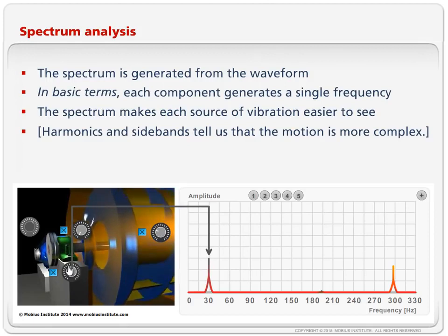But anyway, if I take one measurement and then I come back later and I see 30 days later it's like this, 60 days later it's like this, I can say, okay, the unbalance is growing. And I can decide whether I want to do something about this high level of vibration. Do I think this is going to cause the machine to fail, the structure to fail? Is it creating noise that's creating a quality problem or a noise issue for workers and whatever? But the question I should also be asking myself is, is this going to do damage to the bearings?